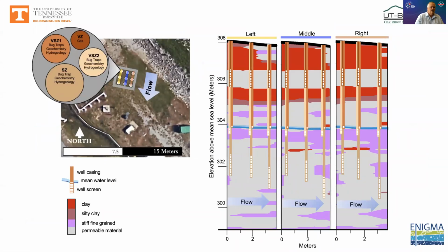On our subsurface observatory, we're setting this up so that we have 2 vadose zone piezometers and 2 variable saturated zone wells and a saturated zone sampling point in each well of 9 wells in a cluster. So we can measure flow going across and in patterns, and then up and down gradient.